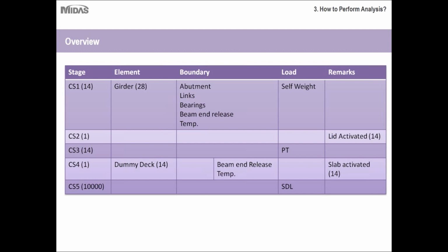They are applied at the bottom of the U girders. So we'll be using links to simulate that, and then for modeling the bearing or the interior supports, we can use some type of elastic links, or directly a point support with some degree of translation allowed. Then in the first stage, since we are not adding any external load, it will be just the dead weight of the structure erected so far, so we will be considering its self weight.